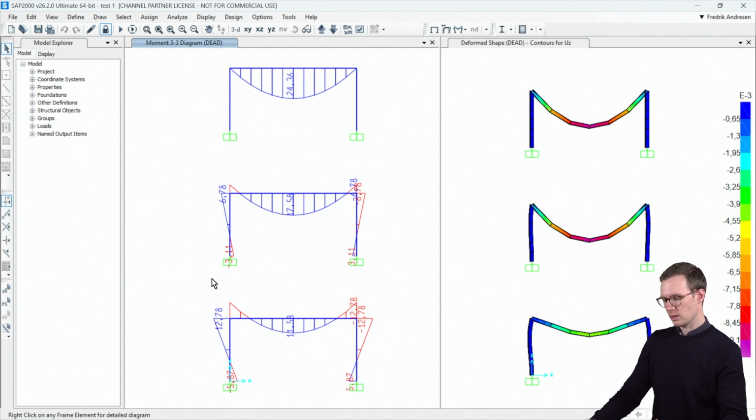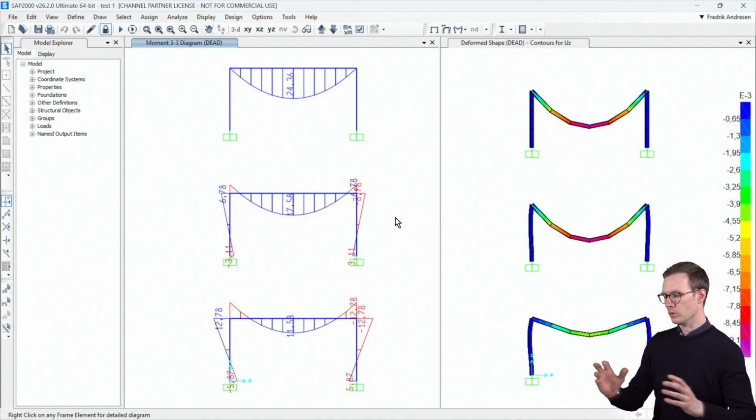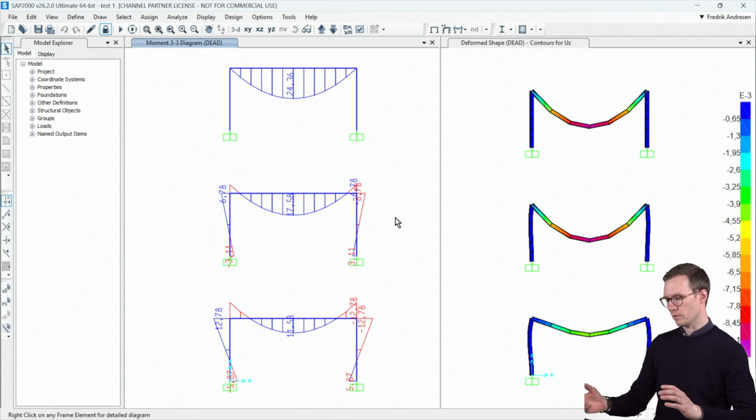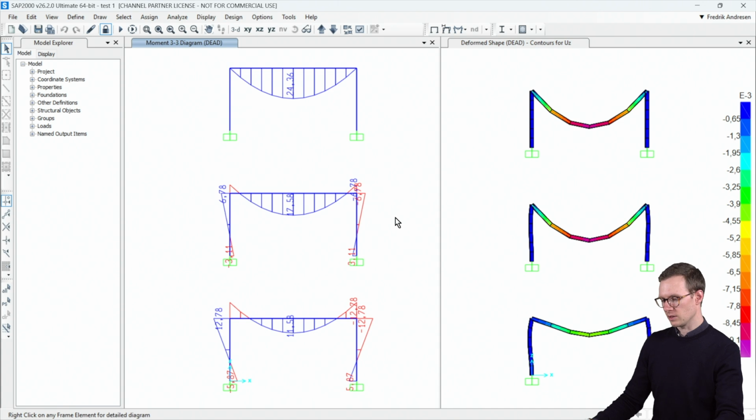So this can give more flexibility on how to design a global model. It will also make the results different over the whole structure and how the forces move through the structure. So this is definitely something you need to consider for some cases. And the next step is then to synchronize the checkbot model so that you can have the new forces applied to the connection, and then you can run the connection design.